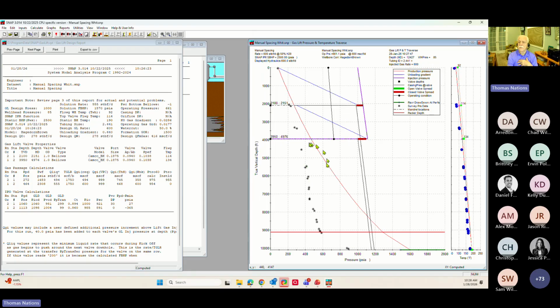All right, so we've got to the second gas lift valve so far. Woohoo, good deal. All right, so how would I place the third one? Transfer pressure to get to here. Then I got to pick a transfer pressure here, right? So that's roughly, well, I got an XY coordinate right here on my graphs, all my graphs. So I want to put it somewhere right there, right?